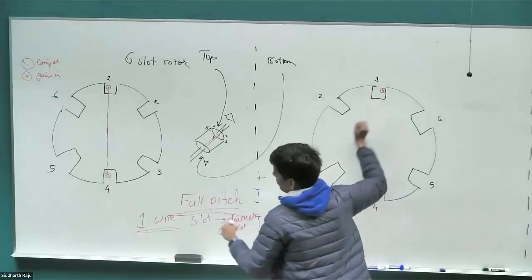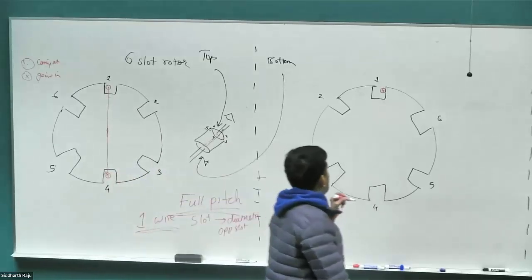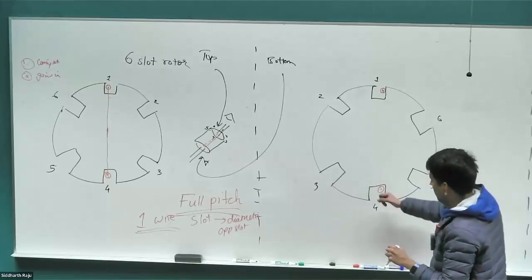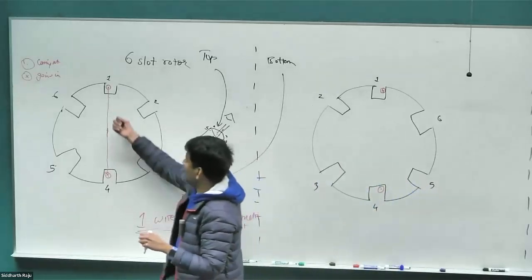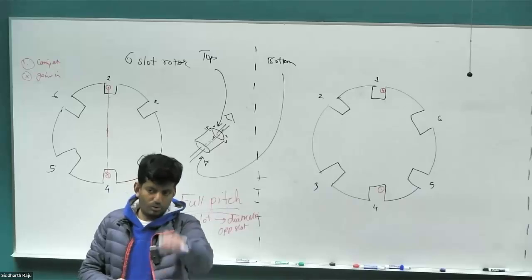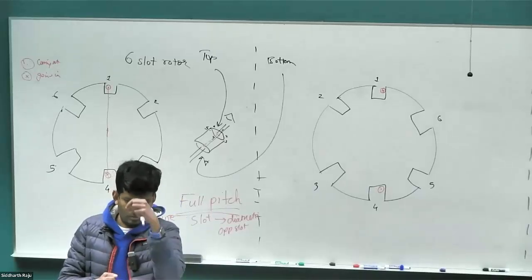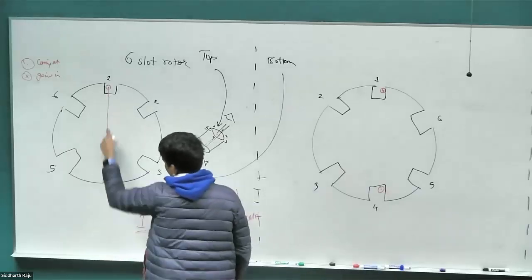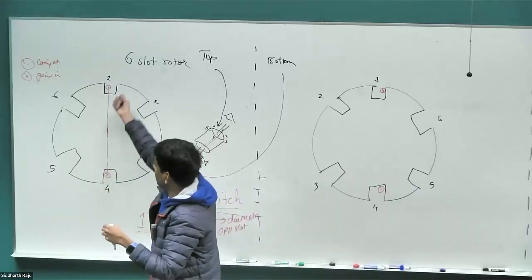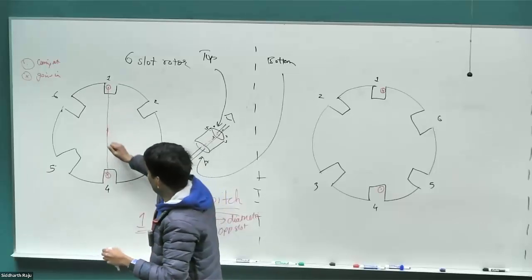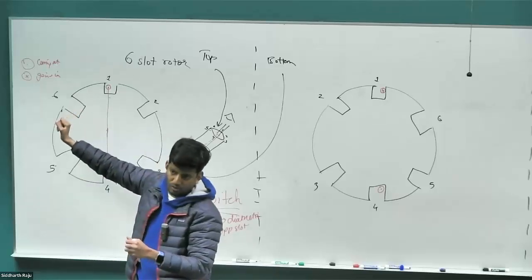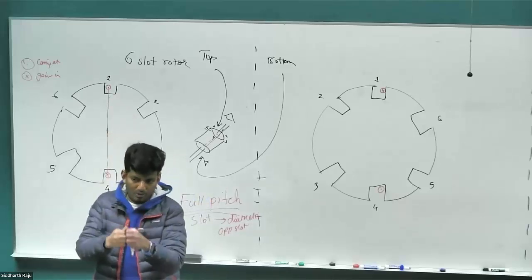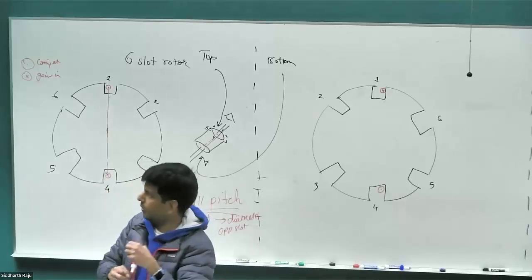So the conductor comes from slot 1, goes into slot 4, and in the bottom view that is going to appear as if it is coming out of slot 4, okay? Now one thing we can do is do this winding multiple times, going from slot 1 to slot 4, slot 1 to slot 4, slot 1 to slot 4, all right? So each of the slots that you saw on the motor that I passed around, you would have seen multiple turns going from one slot to the other. So whenever I draw this line, it is indicative of say 10 or 20 or 30 conductors doing the same winding in the same slot, right? When I use a different line, that means it's a whole different set of conductors going into a different slot. Just to keep the diagram clear, whenever you see a winding diagram, they would usually only show one wire, but that is indicative of a whole bunch of conductor turns in that one particular slot, all of them indicated by that one single line that I've drawn here.